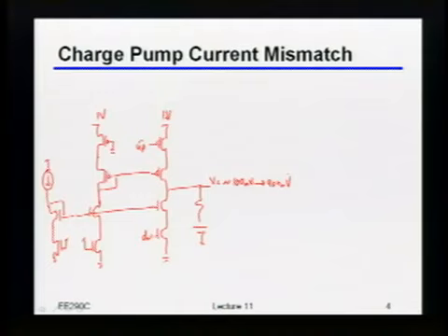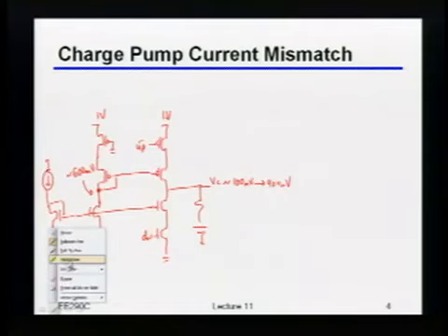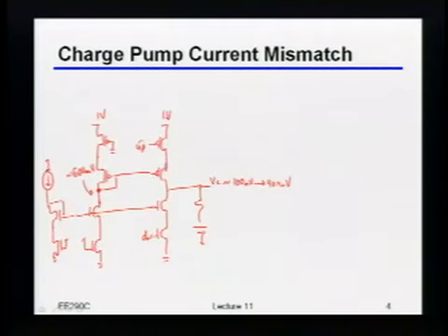On the lower end of a control voltage, your pull-down current will be lower than the... Yeah, that's right. Basically, we're starting to squash out that bottom current source, right? Just to make that clear, if I look at the biasing branch, the voltage there is approximately 600 millivolts. So clearly, when I do this mirror over here, the current I get through that PMOS is not at all the same as the current I got through this PMOS. Not to mention, of course, that the NMOS isn't really the same as this guy, because the biasing may not be, the output impedance may not be good enough to really tolerate that, okay?